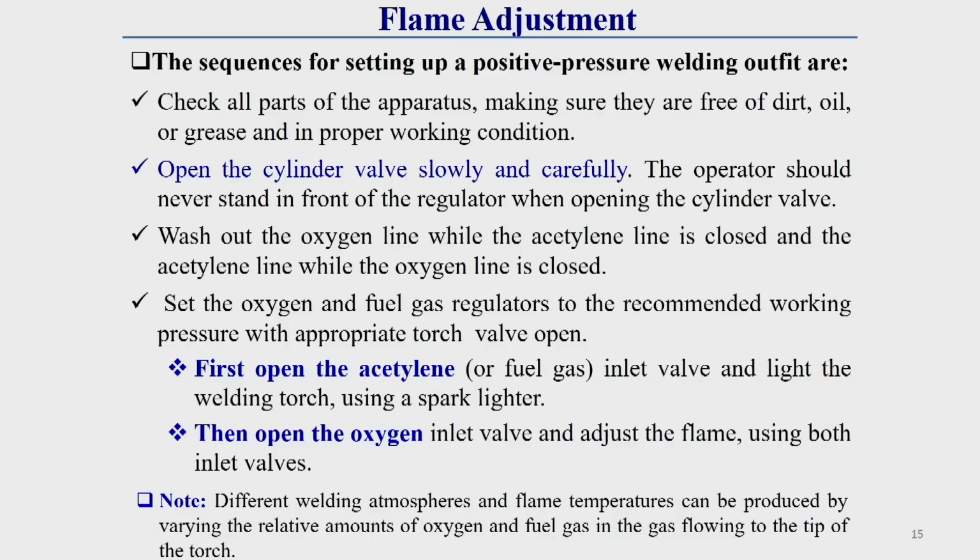That means the operator should not stand in front of the regulator. Because during the opening of this valve, there is a chance of the regulator being blown off the cylinder, and that can create an accident. That is why the operator should stand beside the regulator.